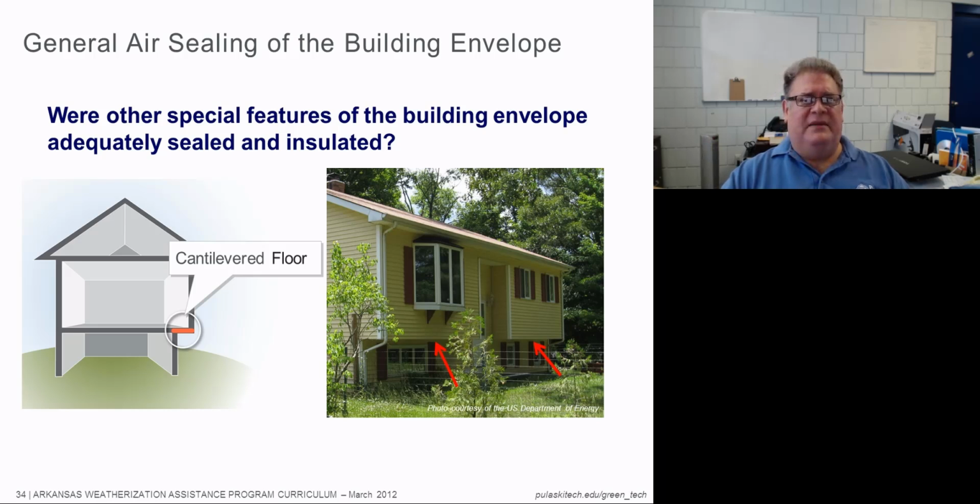The air temperature may be at a good temperature. However, the difference between body temperature and the surface temperature of that wall may be great enough that it's making someone in there uncomfortable, either because they're picking up heat from that wall, the wall's radiating heat to them, or they're radiating heat to the wall and they're feeling cold and clammy and chilly in there, but the air temperature itself is good. And that may be because we are bringing in and cooling down the inside of that wall too much, and our insulation is not working. So at that cantilevered floor, we need to treat it.